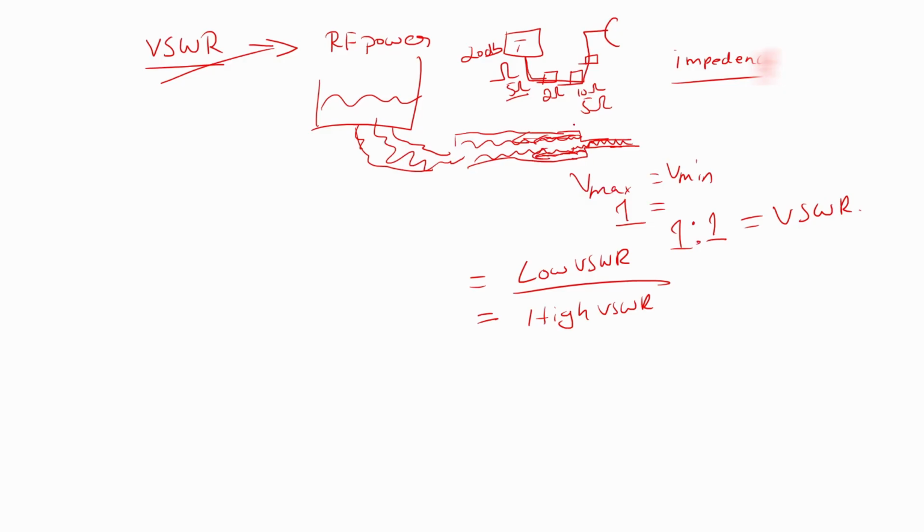That reflection will create a bad signal, and all of the signal is not absorbed by the antenna. So how to avoid this is to have the impedance common across all the components. While purchasing, you need to choose so that the impedance is almost the same.